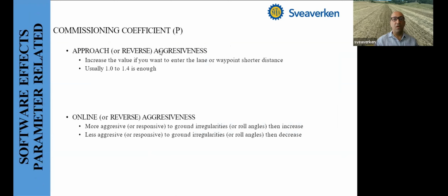So the terrain compensation is not used on flat surfaces, only side slopes. So actually here we should understand the exact solutions in our hand in the parameters section. We can only change these three different values and correct the S-bend behavior of the vehicle on the field.